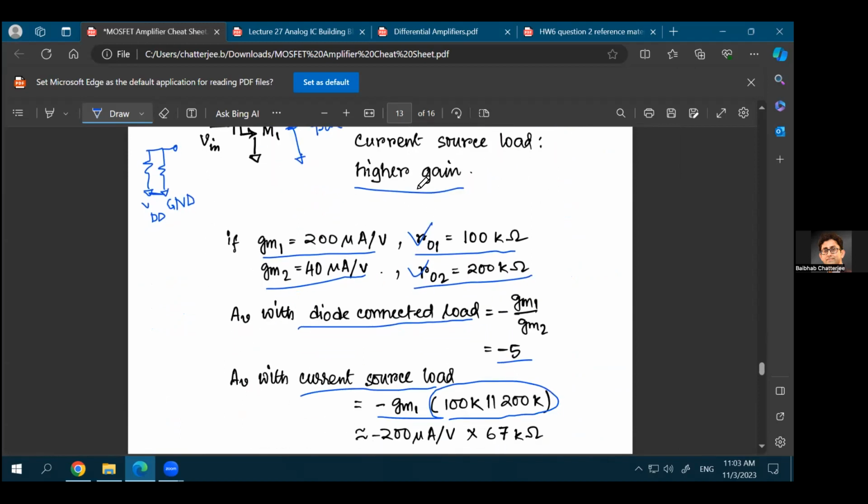So that's a great question. It's the same trade-off that we saw for op amps. Now we know why that happens. This is an explanation that if this circuit is inside your op amp, this already gives you the reason why, as you increase the gain, your bandwidth reduces, and if you reduce the gain, why your bandwidth increases. So that's a possible reason if this circuit is inside the op amp.